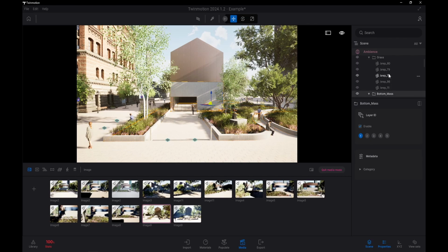And then, for example, ground. If I go to ground, I don't know where it is because these are all over the place. But if I forget how I did my layers, if I do ground, I want to give that a material ID of 2. So a grass border, let me enable this. And I'll give material ID of 3 with all this as well. I like to double down and do it like that. So I want that material ID of 3. So I want this to be separate.